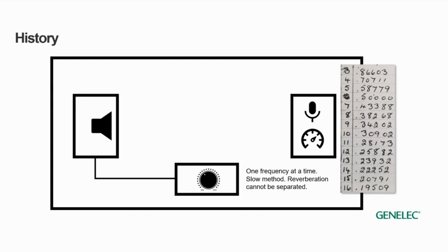Then we work through the full audio range of frequencies, and what we end up with is called the frequency response. This tells us the audio level and how much variation in the level we have across the audio range of frequencies. Ideally, with the constant input level, we expect to see a constant sound level at the listening position. If this is not the case, we have coloration, and the monitor may therefore exaggerate or underpresent certain details in audio. Usually, most of the variation that we see in this kind of measurement doesn't actually come out of the monitor. The most likely reason for the variation is actually the room and where we have placed the monitors and the listening location in the room.